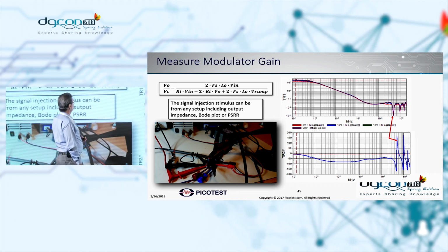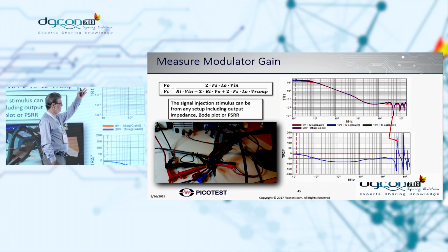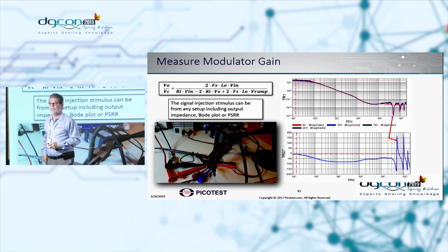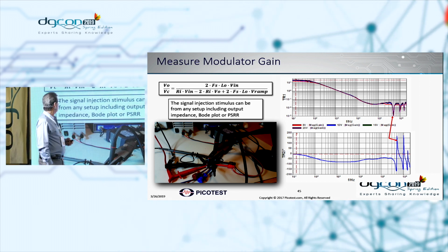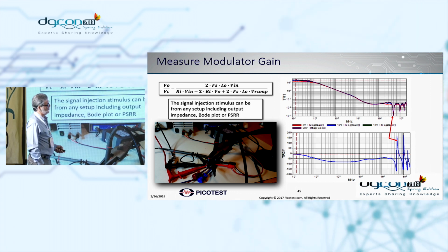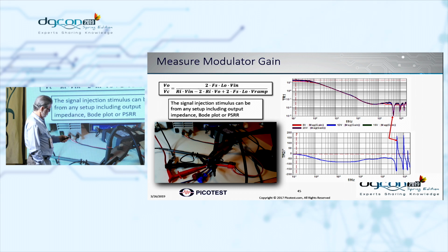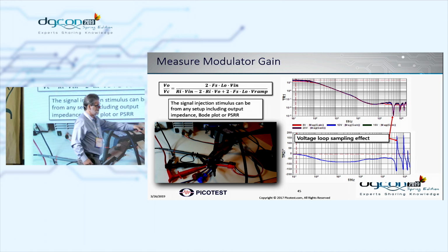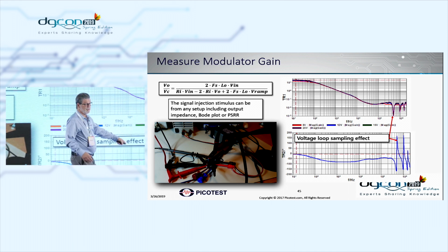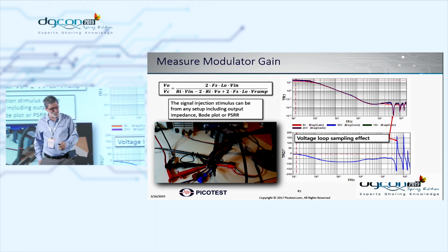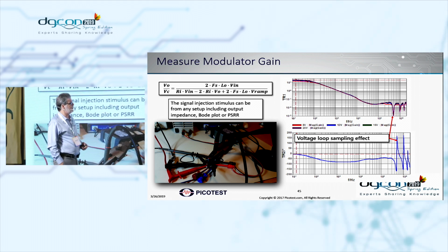How well does it do? Here is our Bode plot. And you can see the comparison between the simulations and the measurements. They're nearly perfect. And if you want to solve that equation, you can. And if you don't want to, you don't really need to. I wanted to point out that here's the transmission line effect that shows up due to the sampling criteria. And so our model doesn't necessarily show that, though we can include it if we want to.